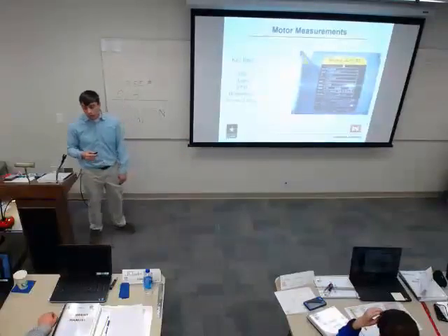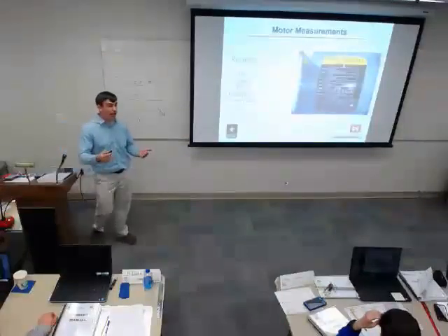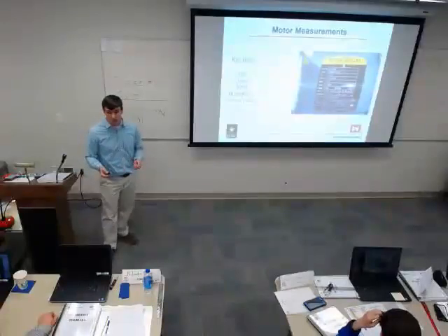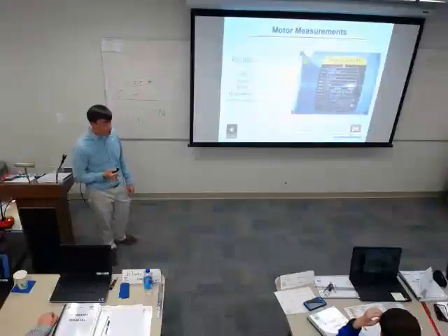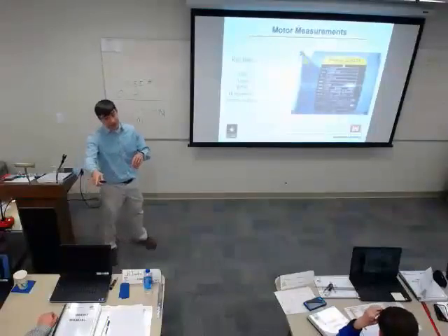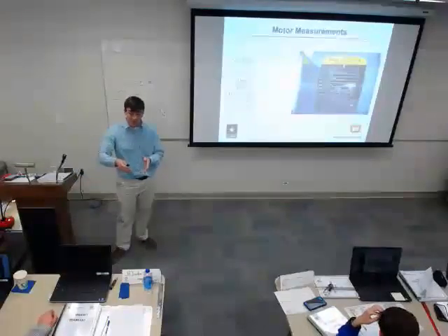So if you haven't heard that situation, you're going to have a contractor ask you, can we just run it in the service factor? And the answer is no, you cannot. You need to get the next size motor up, or go back and figure out why you're needing this extra power.